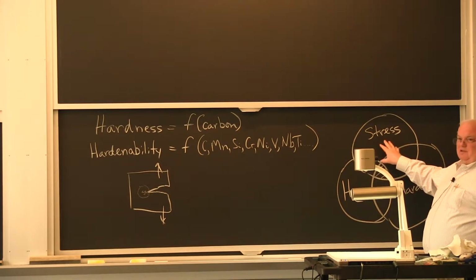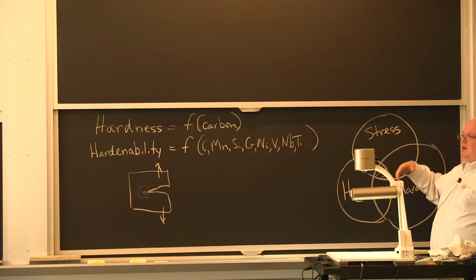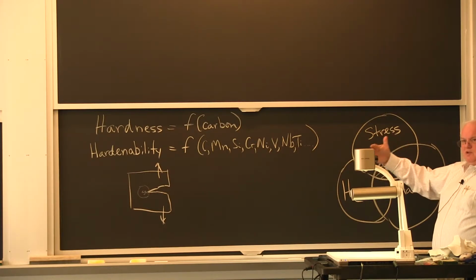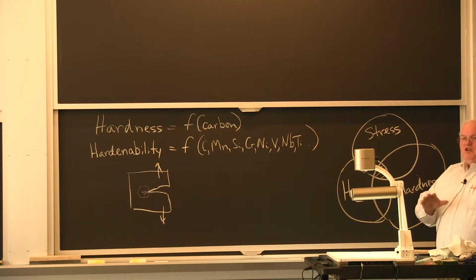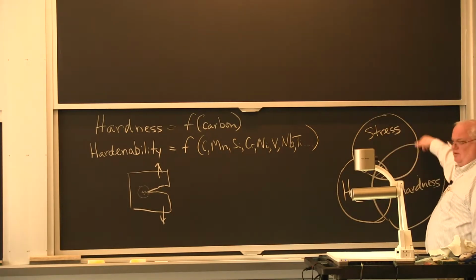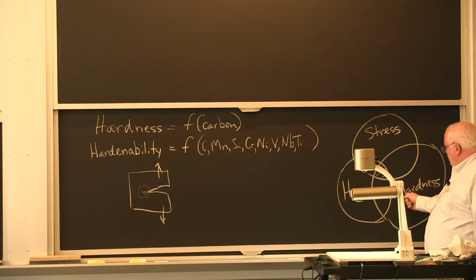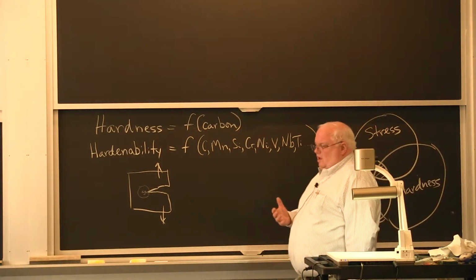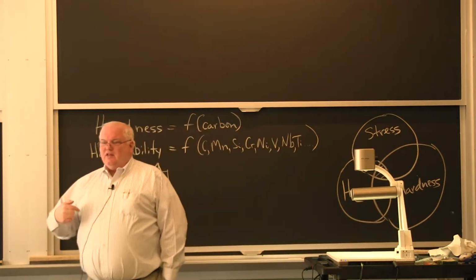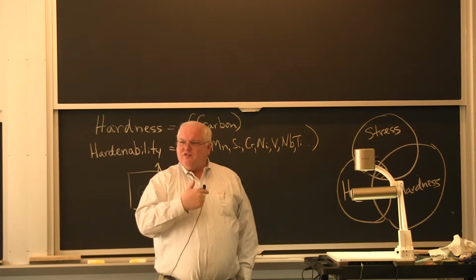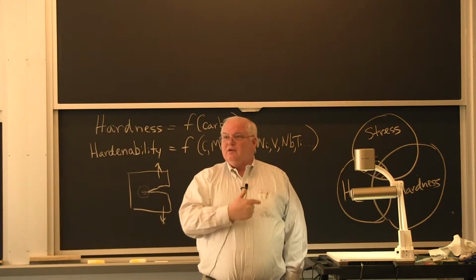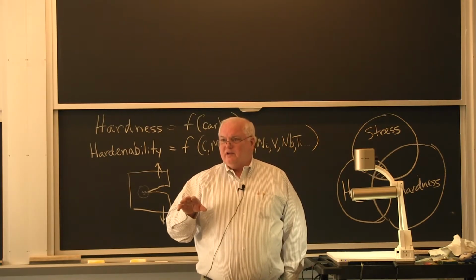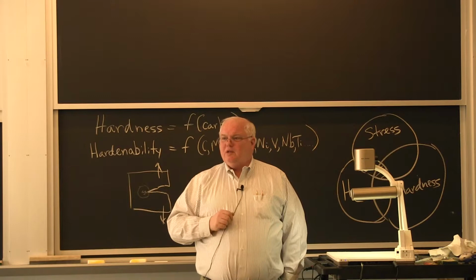It's the high strength steels, the things we use for nuclear submarines, for bridges when we want to save weight, and we're using 100 KSI steel. You never would weld on an aircraft landing gear, okay? Forbidden. 250 KSI steel, I mean, you've got a huge stress circle there. The only thing you can do is get rid of the other two things. So you've got to get rid of at least one of these, and the higher the strength of the steel, the more careful you have to be, maybe working on several approaches to avoiding hydrogen cracking. Mild steel, not a big problem.